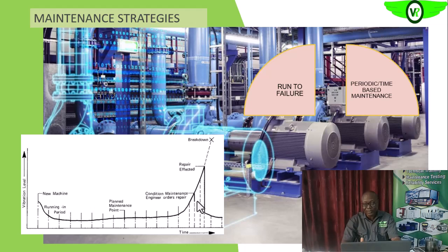So it could be recommended that for this particular motor, when you subject it to this kind of condition, after 2 months, 6 months, or 2 years, do a bearing change out. That will now be what informs your preventive maintenance program. That is what you will look at in designing your preventive maintenance program.